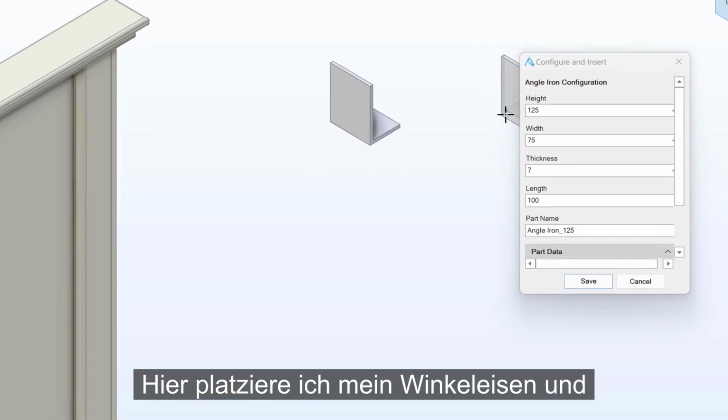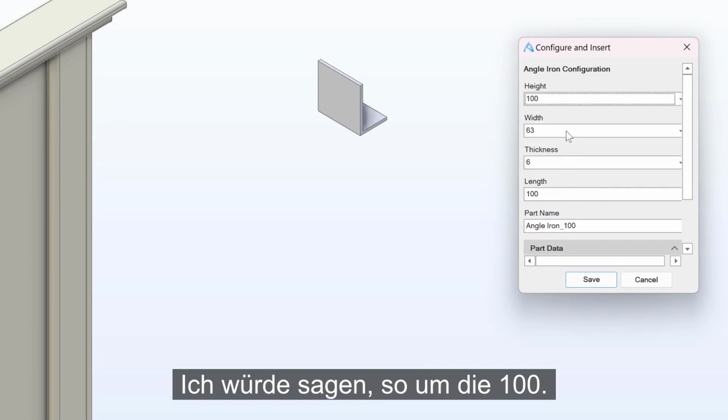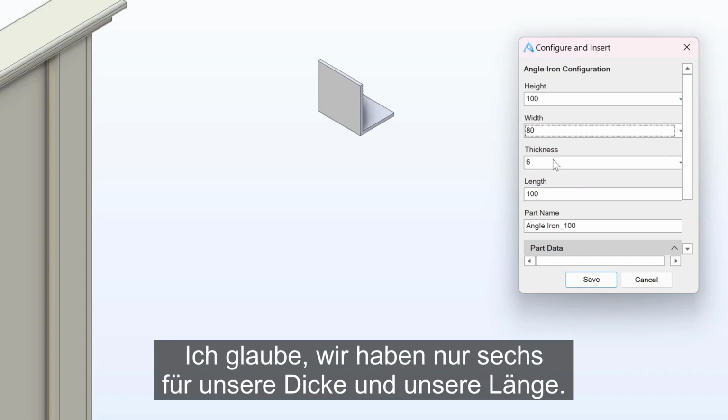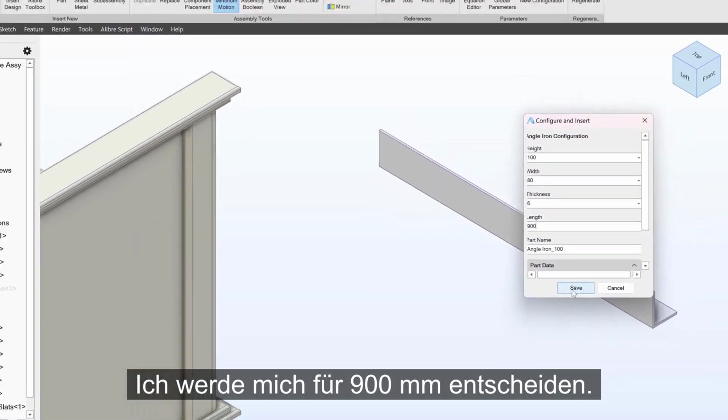I'll place my angle iron here, and I can choose between a wide variety of heights. I'll go with something like 100. We have 2 options for our width. I think we only have 6 for our thickness. And our length, we can make it whatever we want. I'll go with 900 millimeters.